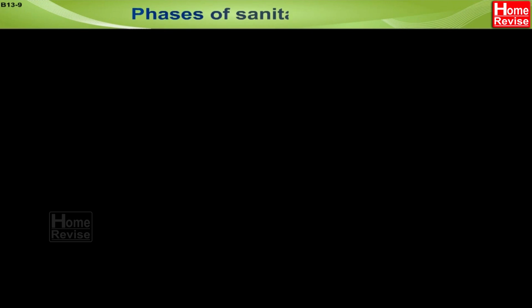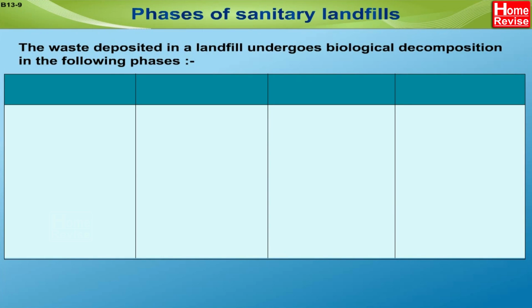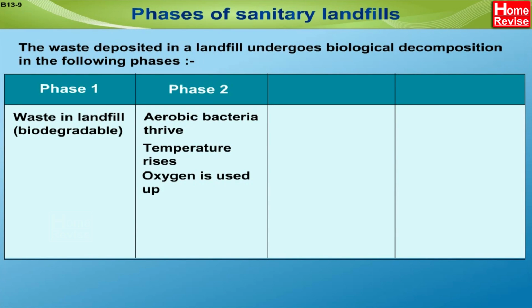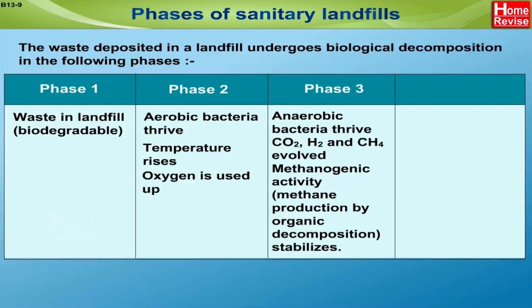Phases of sanitary landfill. The waste deposited in a landfill undergoes biological decomposition in the following phases. Phase 1 is waste in landfill, which is biodegradable. Phase 2, aerobic bacteria thrive, temperature rises and oxygen is used up. Phase 3, anaerobic bacteria thrive, CO2, H2 and CH4 evolve.